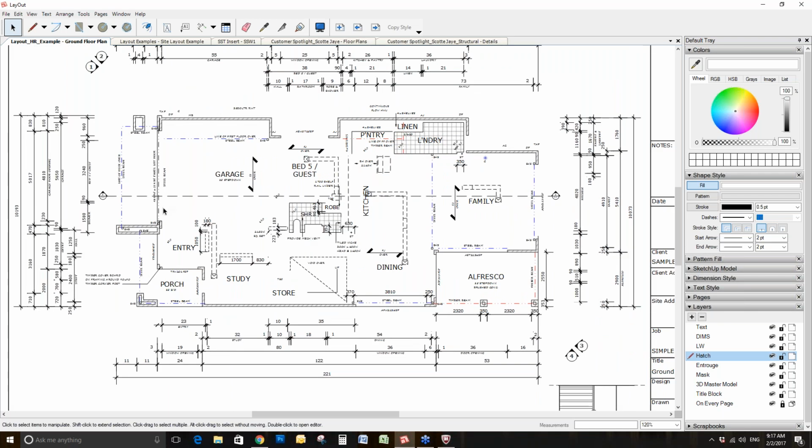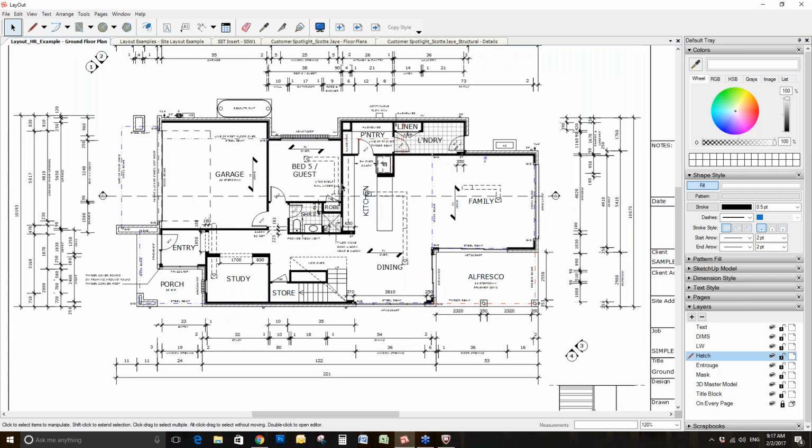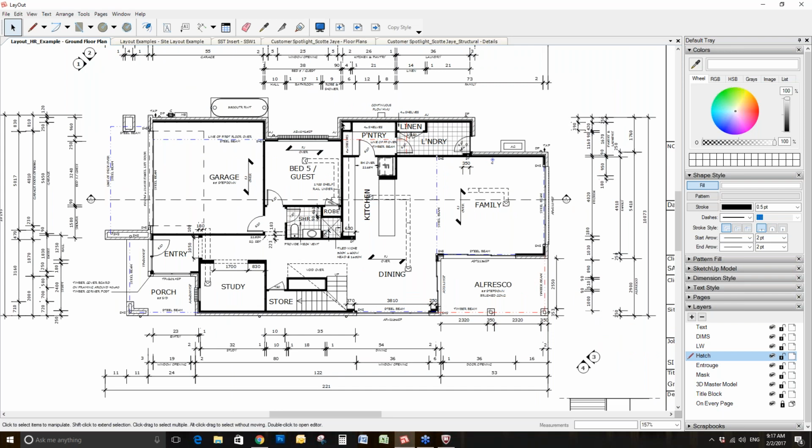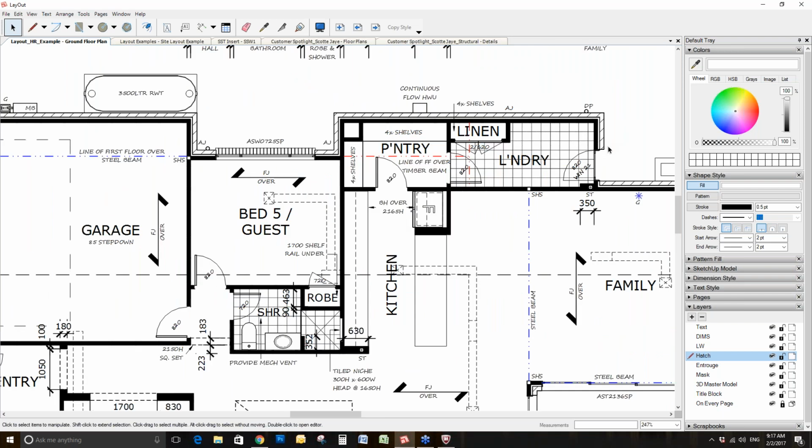There's certain things that you want to put in. This was done in an old version where there was no smart hatching in PlusSpec, and we will talk about that, because now you can click on any SketchUp section and assign smart parametric hatching to it. So hatching, colors, textures, etc.